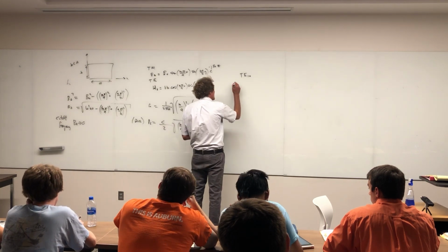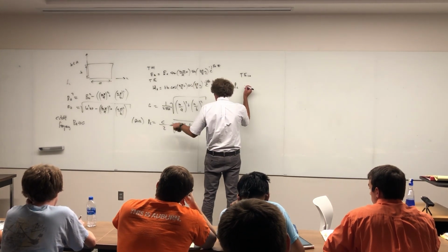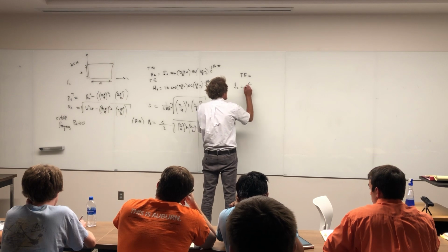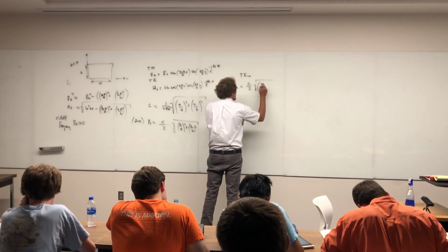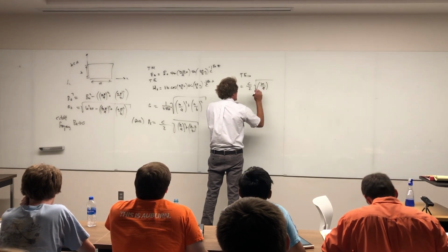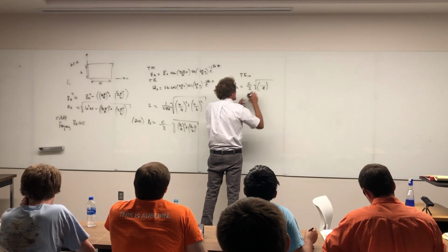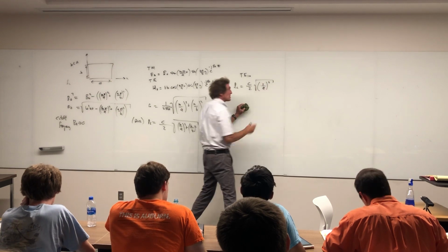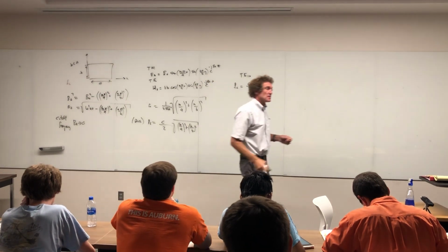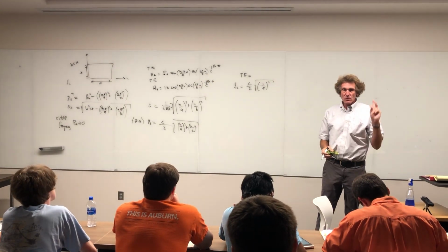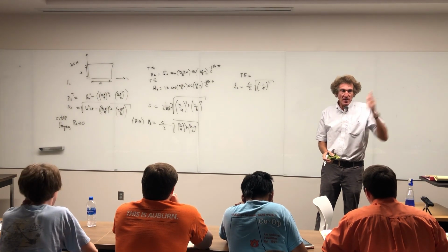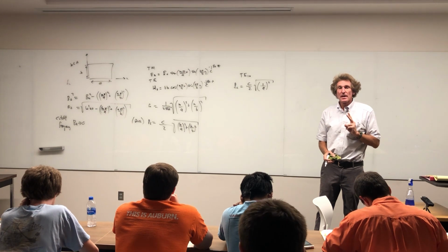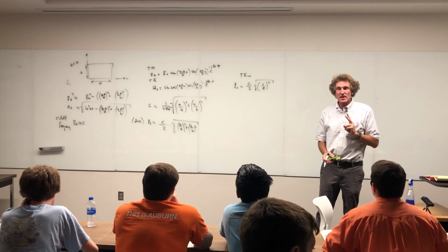And the cutoff frequency for that would be equal to, if it's air-filled, c over 2 times the square root of m over a squared, but here m becomes 1. I want to do this completely here. Do you all see what I'm doing here? Just look at the equation. Put m equal 1, n equals 0. This is the lowest order, or the lowest frequency, that will propagate. Above that will propagate. With me? Y'all see? I'll put the dimensions in a second.